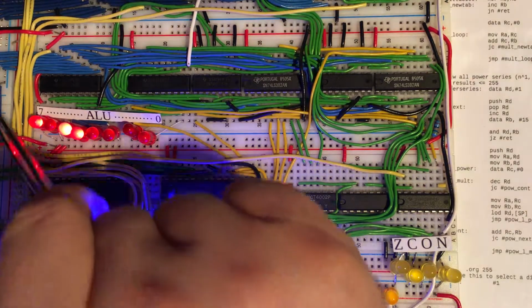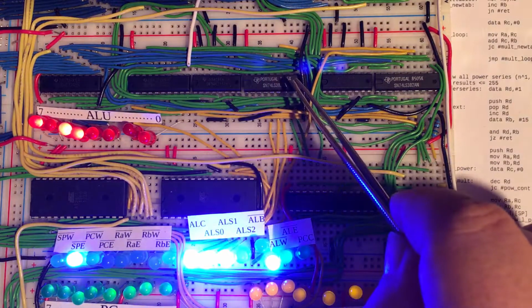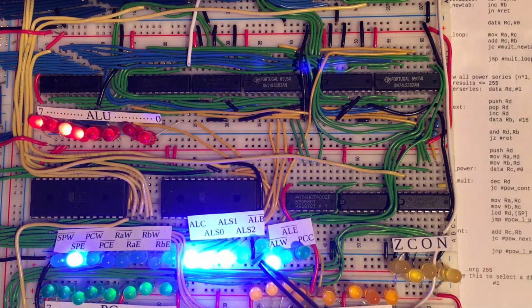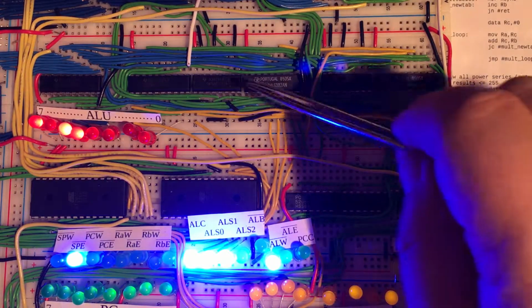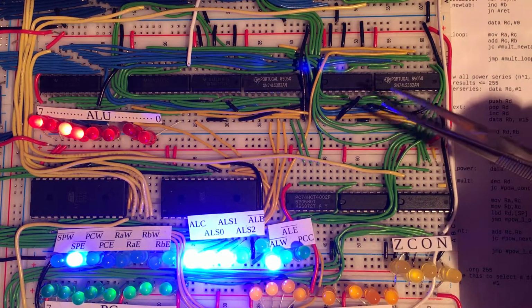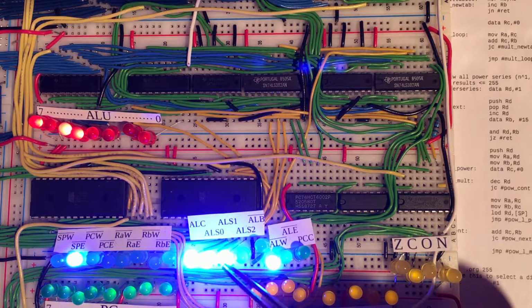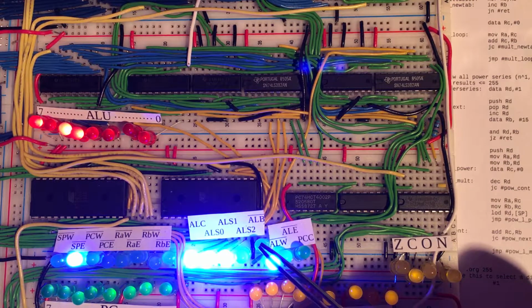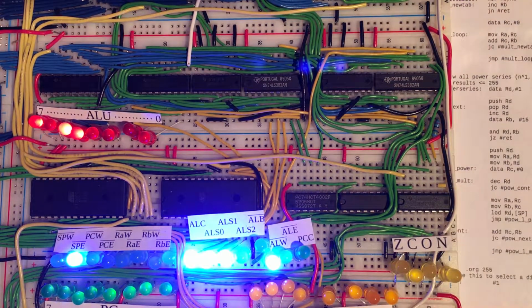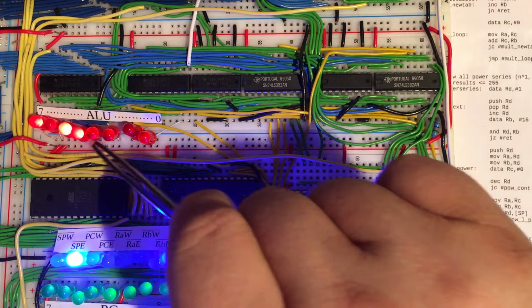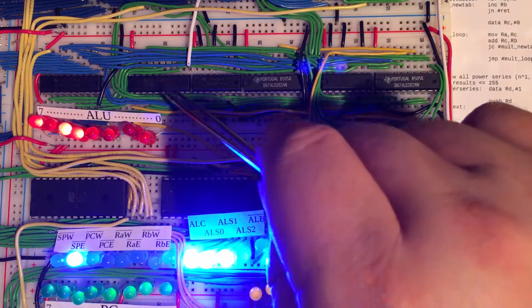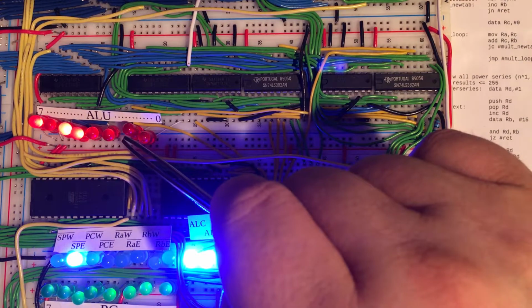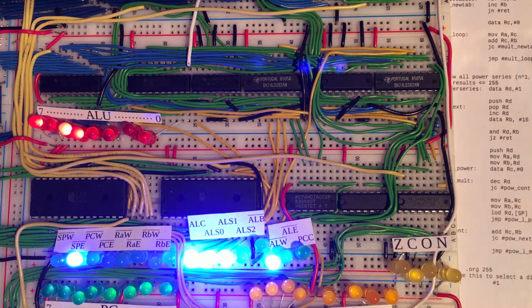And so they're going from the bus into the first operand of the ALU. And the second operand of the ALU, because of this signal, this selector which we've built in here somewhere, isn't actually selecting the B register, but it's selecting the hard-coded value of 1. And so these 4 lines are going to tell the ALU to add 1, but not the B register, to the value which is in the stack pointer, which is in fact also on the bus right now. And so on the next rising clock edge, it should write the result of that calculation into this register, and that should be 254, because 253 plus 1 is 254.